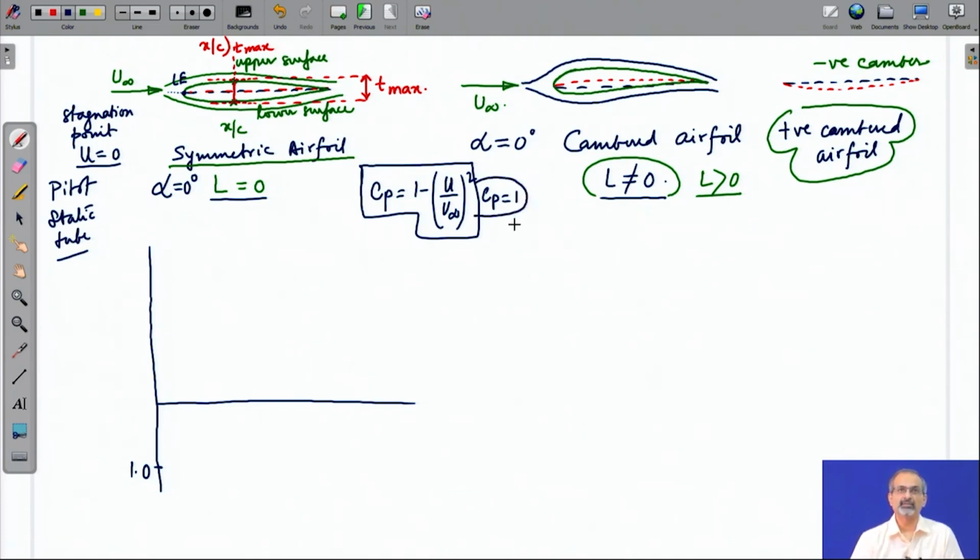So, if you are not considering viscous effects and additionally you are considering inviscid incompressible flow, then that is how it works, that the peak value of Cp will be 1. When we plot the Cp distribution, we usually plot the positive values below and the negative values above. This of course gives you the x by c side, and on the y axis we are plotting pressure.